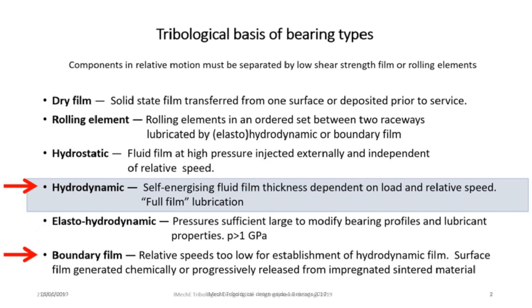Boundary film bearings are those in which the required film of lubricant is not supplied continuously to the bearing, but is gradually exuded out of a porous and previously impregnated sleeve. Porous bronze bushings used for light duties exemplify this form of journal bearing.